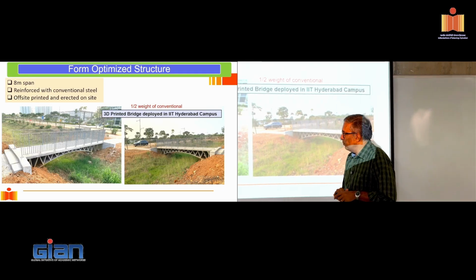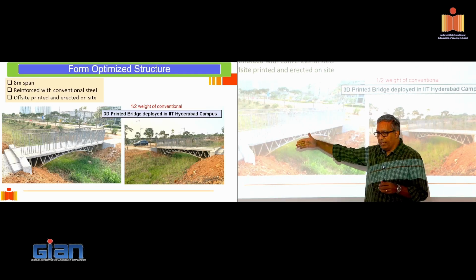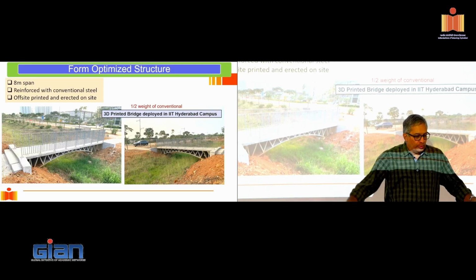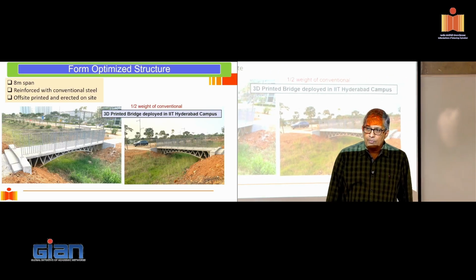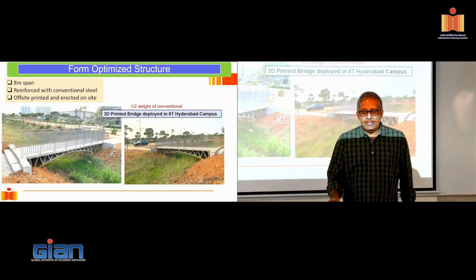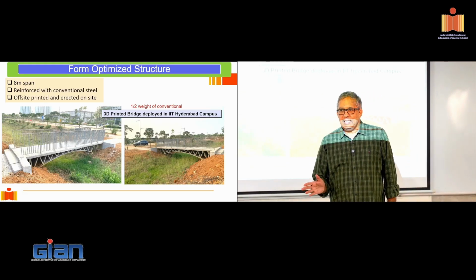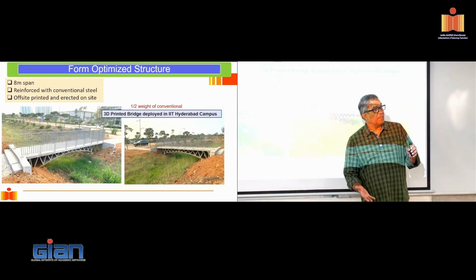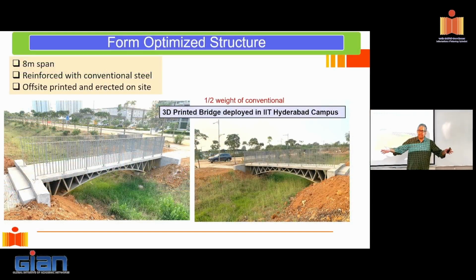Suppose I gave you a problem where I said, design a pedestrian bridge which is 1.2 meters wide over a 7.5 meter span. The best configuration that would work there is a one-way slab. Even in railways, they resort to one-way slabs if the spans are small, 5 to 7 meters typically. So we've done a one-way slab design for the same set of loads and compared to that.